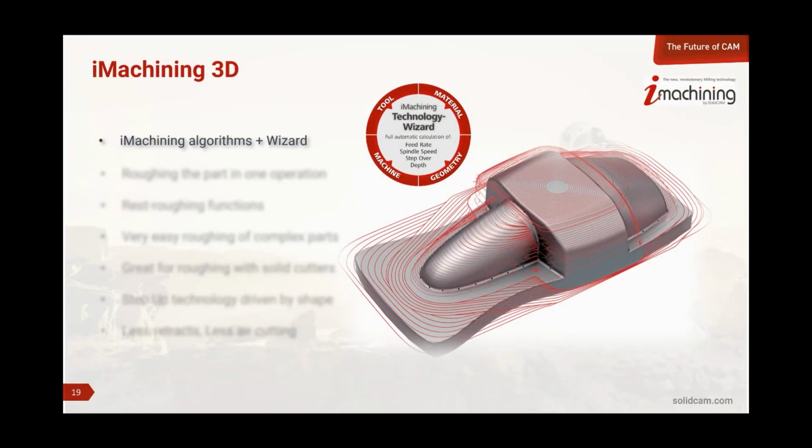The iMachining algorithms in Wizard are operating in the same manner and fashion as they were in 2D, but they're based on the 3D toolpaths, or the 3D shape of the model. In many cases, not always, but in many cases, we can rough out the entire part in a single operation. It does rest roughing functionality, automatically picking out smaller corners with smaller tools.